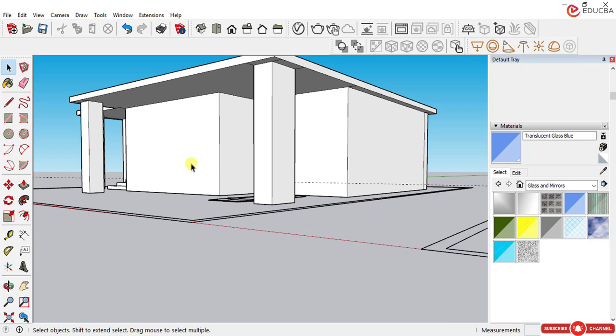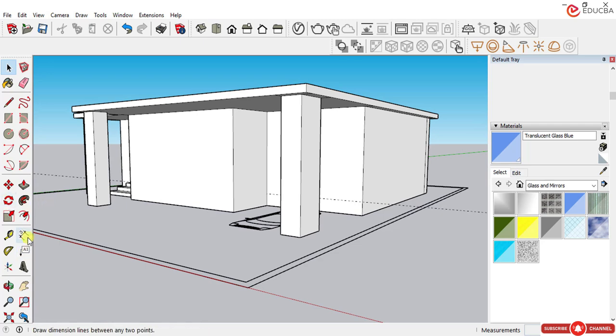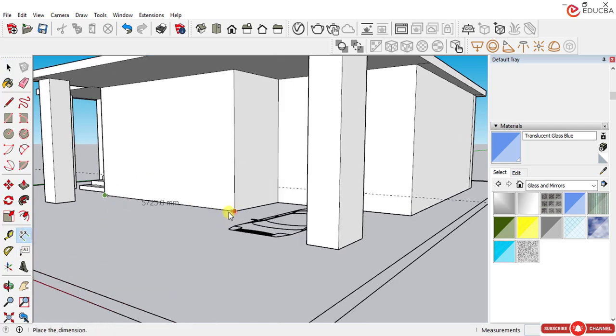Now same thing here I will do. Here the width of the glass will be 2 meter and the height of the glass is 2.4 meter. So here what I can do, just provide the big or wide glass like 3 meter by 2.4 meter. Like this. If the length is 5.7, I can give the center point here, and from the center divide it into 1500 here and 1500 here.